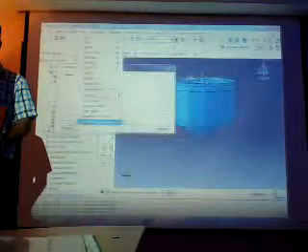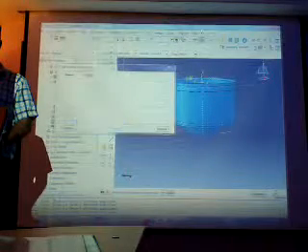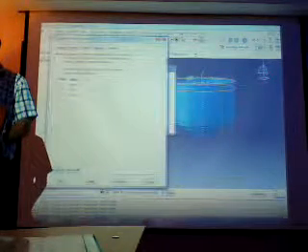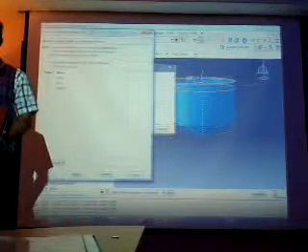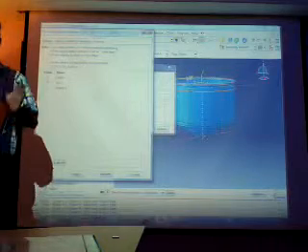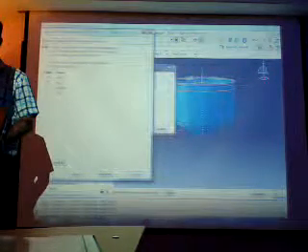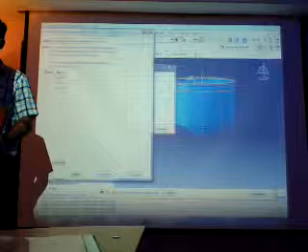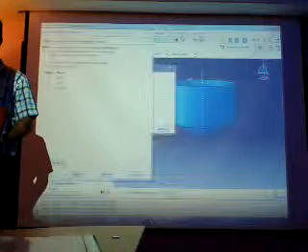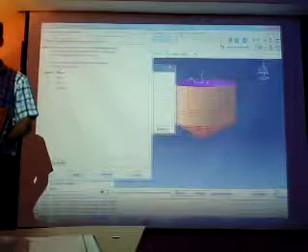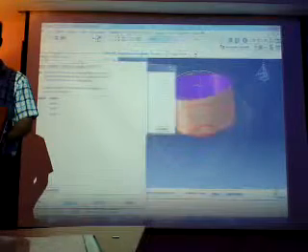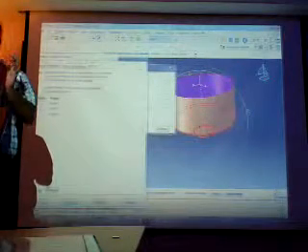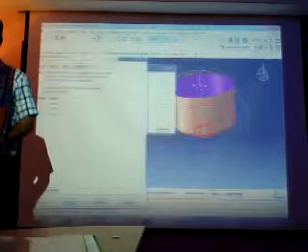As you can see here, select the first surface. Again, I am going to take the assembly display option. In interaction, we have two different surfaces, master surface and slave surface. Normally, we take a discrete rigid as the master surface. This is my die. I take all the part and done. You can see here we have two different surfaces, brown and purple. We need internal interaction, so it's important to take that here.